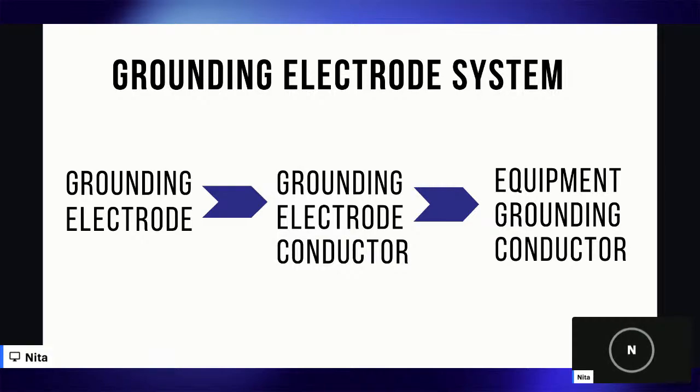Conductive, again, just means that something allows electricity to pass through it very easily. So a ground rod is a metal rod, typically at least about 8 feet, that is driven into the ground. You can use a metal water pipe, concrete encased electrode, but just think grounding rod.